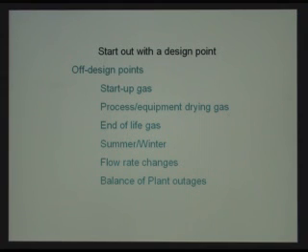Usually for drying, this lasts for many, many days, so that is a long-term operational consideration. End-of-life gas, either the end of the plant or the end of the field. Mole weights coming out of the ground usually change with time, and if we have a feel for what the end-of-life gas might be, we would want to know that so that we can either plan for it up front or at least make it known to the compressor vendor so that he can add some additional capability into the machine to handle end-of-life gas.